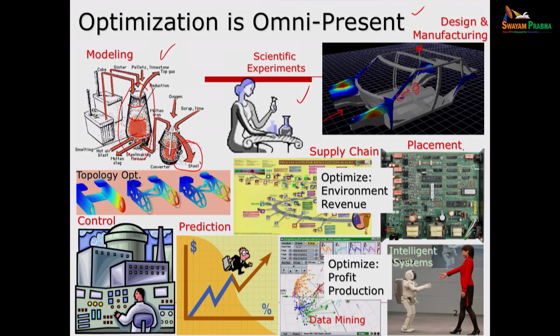Placement optimization is another thing. Here you have a small board and you have to put a lot of things in there. Some of them are connected to each other. So in order to minimize the overall wire length, maybe you want to put those that are connected close by. But then, because of switching on and off between them, this part will get heated very easily, and they call these in electronics design hotspots, and you don't want that because then these little elements are going to go bad pretty soon. So you want to spread them.